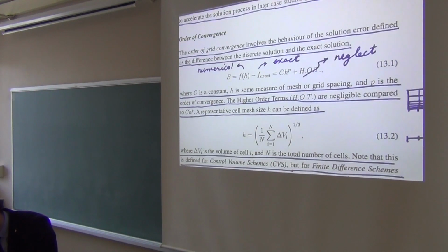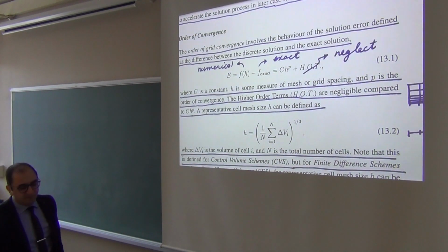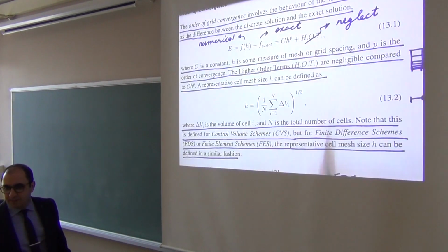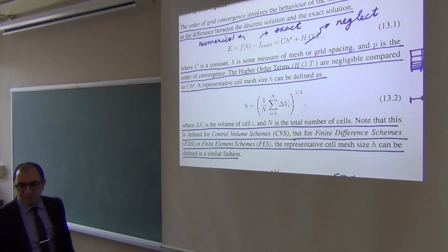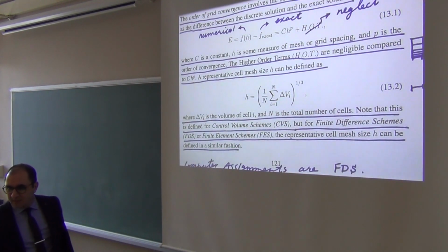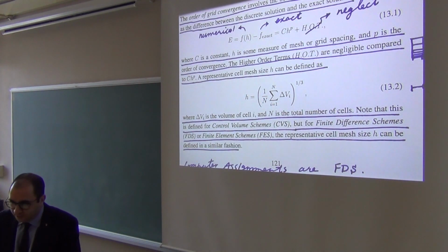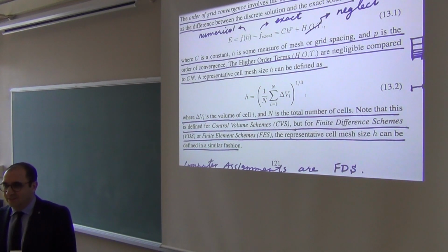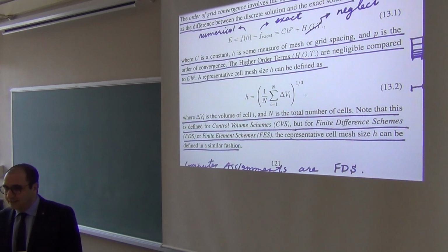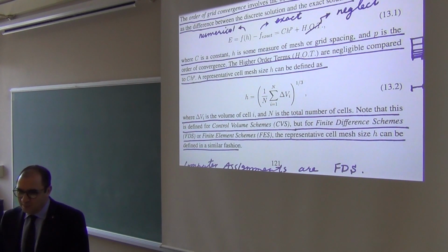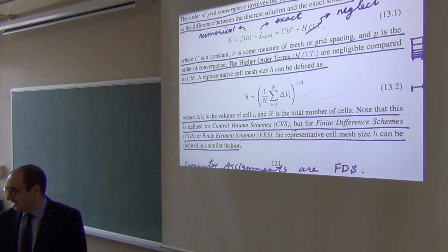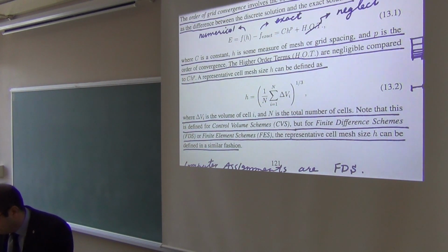A lot of models out there do that. They offer flexibility to the user. For example, their time stepping is variable, so the model can simulate the transient process as fast as possible without diverging. It gradually increases the time step until the solution behavior gets iffy, and if that happens, it reduces the time step again. So it dynamically adapts the time step.